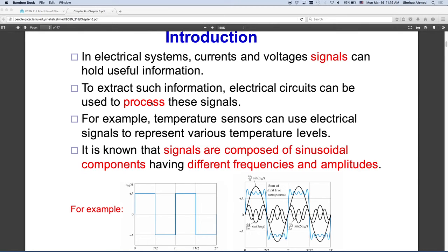Is it happening at the same rate as the equipment is being heated, or does this resistance have some time constant to heat up? May or may not. It's a mass. A mass will have a thermal capacity, right? So you would need to make sure that this thermal capacity will not delay the change in temperature, the measured temperature, so that you know what the real temperature is of your physical system. So even a small resistor that's used as a temperature sensor will have its own transfer function, right?